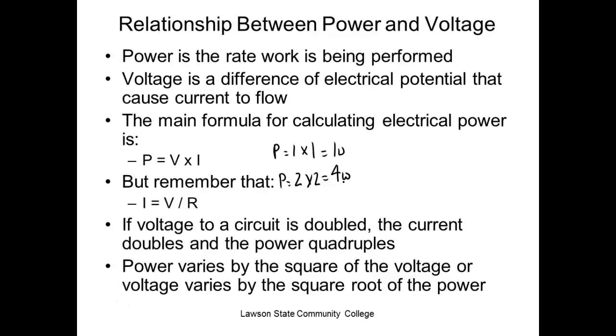And this gets people, you can get people on that all the time. You say I double the voltage to a circuit, what happens to power? They say, well, it doubles. No, it don't. It goes up to 4. Well, if you triple the voltage to a circuit, what does it go to? 9. If you halve the voltage to a circuit, what does it do? Quarter. Drops down to 1/4. So if it goes down, it's 1 over the square. If it goes up, it's the square. Okay, y'all follow this? Yes or no? So power varies with the square of the voltage. Up is times the square. Down it's 1 over the square, right?